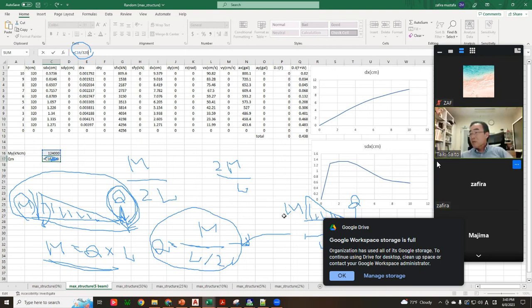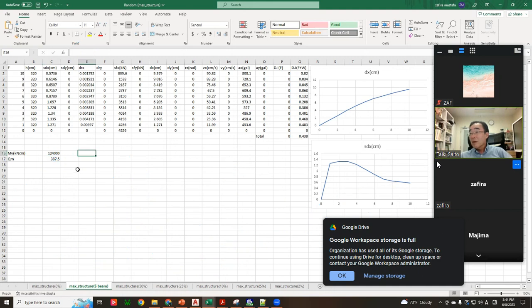Okay. So your beam is yielded by My. And at that time, shear force is this 300, I cannot see. 320. No, could you click? 387, about 400. Yeah. So this is a source of supporting beam. So metallic damper must be weaker than this one. Otherwise, the supporting beam will have damage by fracture.